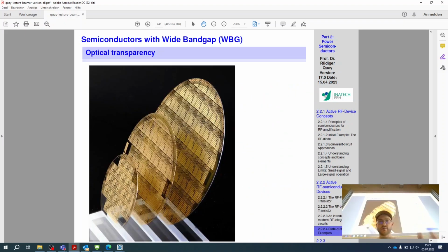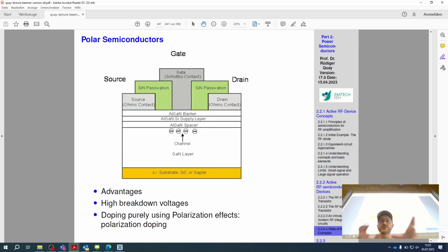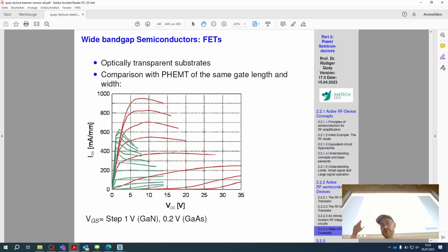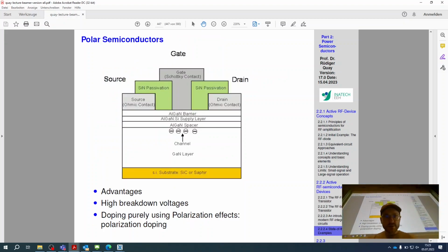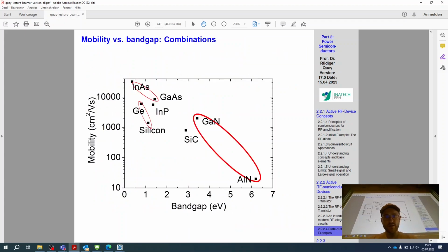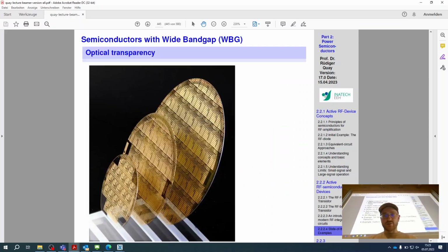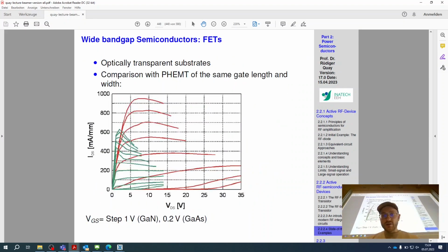We talked about higher bandgap materials, what their properties are, and what polarization effects are used to achieve this 2-DEG layer, which then acquires you a high carrier concentration and carrier mobility, to be able to generate a lot of RF output power. The comparison of a higher bandgap material versus a lower bandgap material was at around 1.4 electron volts, as I saw here, if I'm not mistaken. And then you have GaN, which is at around 3.5 electron volts for the bandgap.